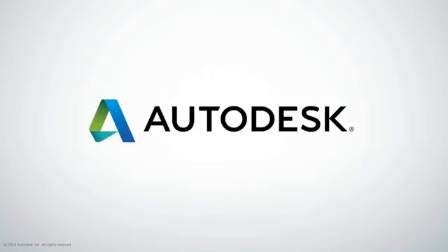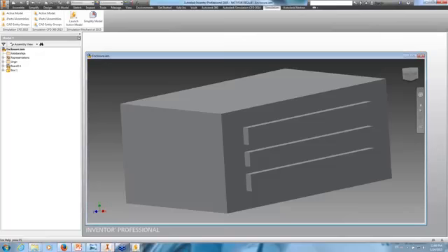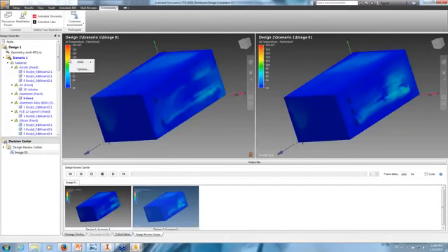The legend bar for different images on the electronics model, is it for one specific design? It picks the worst case legend range and then applies that to both when you do a side-by-side comparison. So that's why it was the same for both. You can then change the legend to whatever range you want for your needs. Like if you want to isolate it to a chip on the board and really make it pop out at a designer view at work.